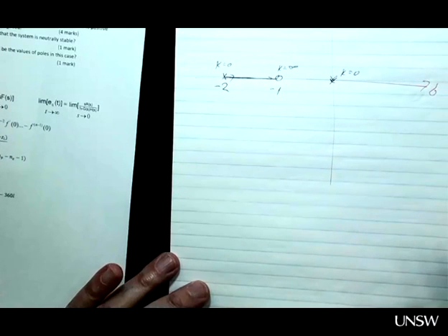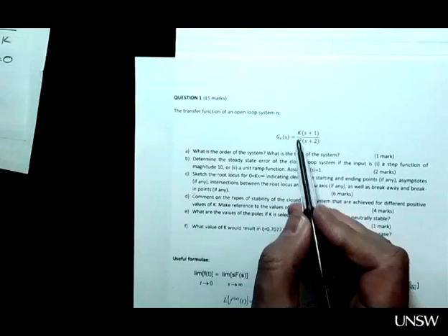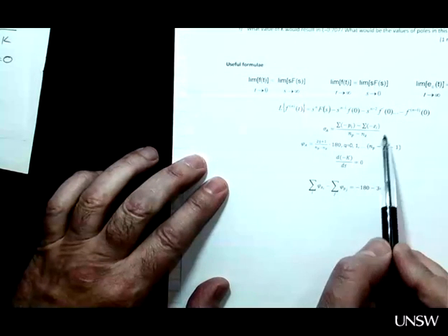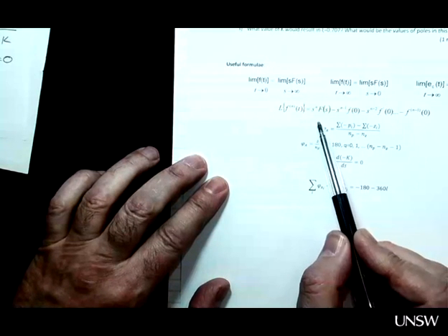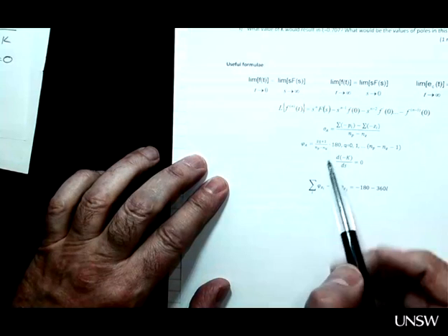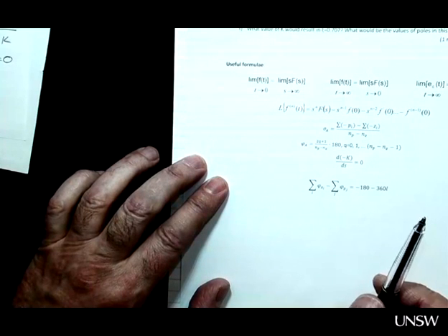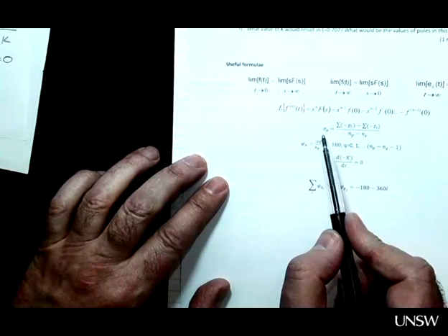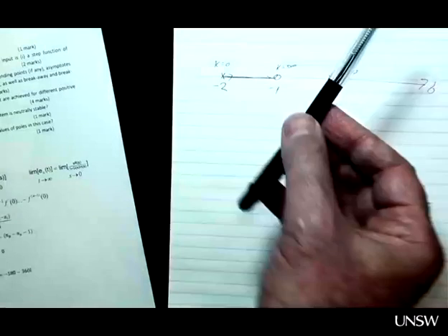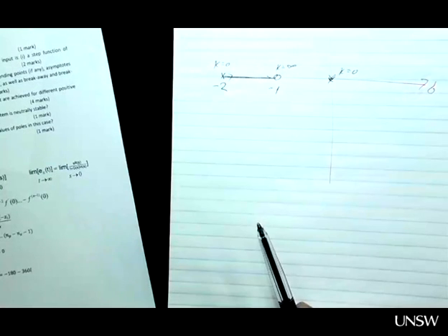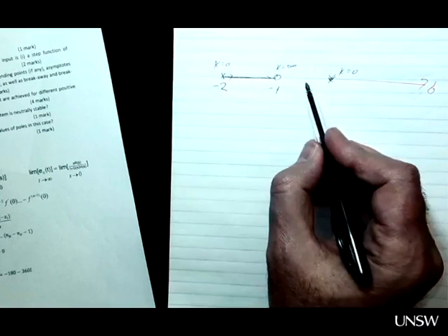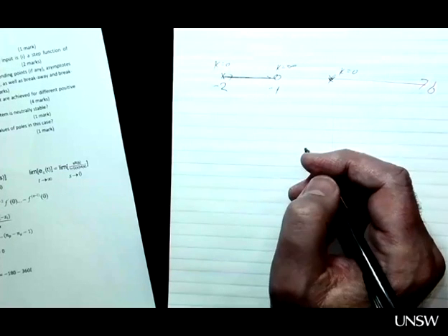Let's see about the asymptotes. How many asymptotes do we have? The number of asymptotes equals the difference between the number of poles and the number of zeros. 3 minus 1 is 2. If you're not sure about that, let's apply equations. Asymptotes are defined by the centroid, which is the point of intersection between the asymptotes and the real axis, and the angles they create with the positive direction of the real axis. Once again, the centroid is the point of intersection between the real axis and those asymptotes, no matter how many we have. That means that no matter how many asymptotes you have, 1, 2, or 10, they all intersect at the same point on the real axis. So that makes it easier. Once you find the centroid, that is valid for every asymptote you have.